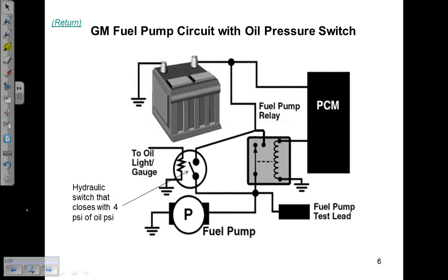Now, here's what's unique about these. Let's say the car comes in, and I've seen this. It's a no start, and it's a no crank. Do your diagnosis, you find a bad starter. Put a new starter in the car, and what you find is an extremely long crank time. You crank it over for 15 seconds, you crank it over for another 15, of course waiting between to let the starter cool down. By the third 15-second crank, the car finally starts. The reason the starter failed in the first place is the owner of the car has been driving it that way for a long time.